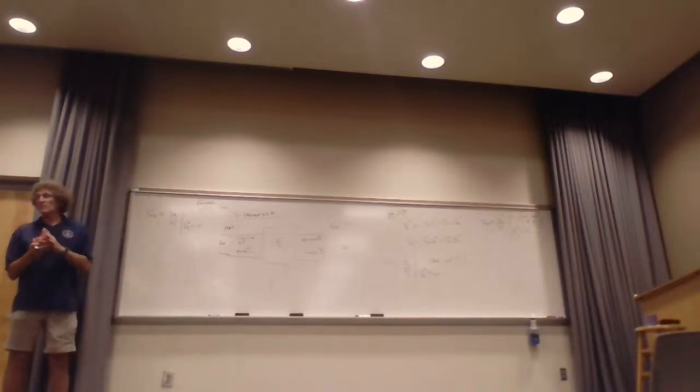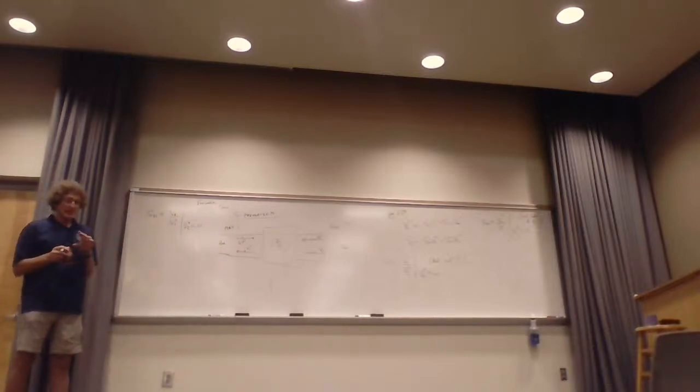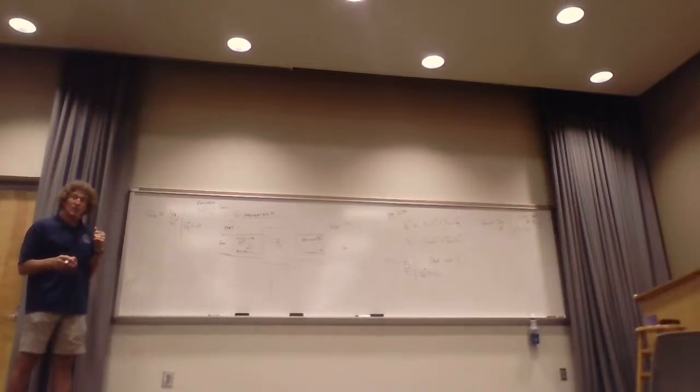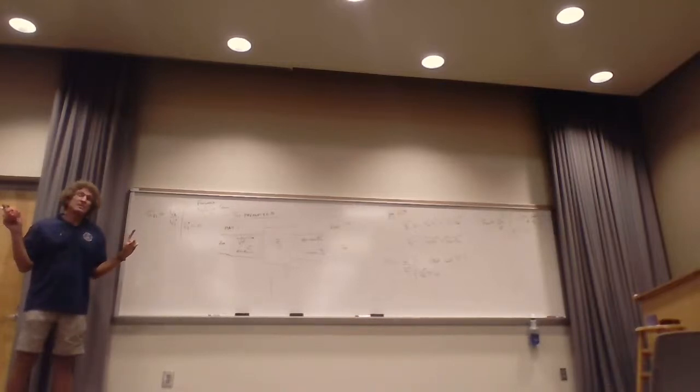And they measure that all the time. When they're analyzing amplifiers and things like this, they'll sweep the input frequency over a range at a constant voltage, look at the output voltage, and get the S parameters, the forward voltage gain. This is the S21. They'll get that over the range of frequencies that are of interest for the amplifier.